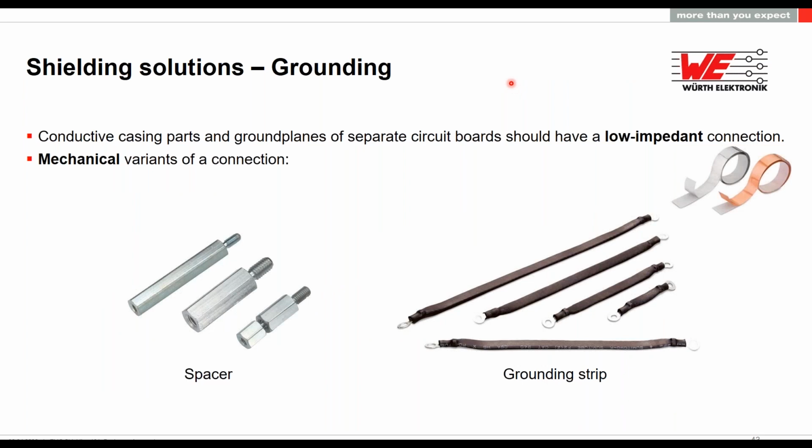Finally, we have these grounding strips that can be used in combination with the spacers to connect the ground to the housing. Normally, the tapes are used for grounding in prototypes, not in final designs. These are made out of twisted wires on the inside in order to prevent as much as possible the pigtail effect. So we need these long distance connections, and there is no other way than doing it with cables. We can use these twisted wire cables designed in order to avoid pigtail effects.